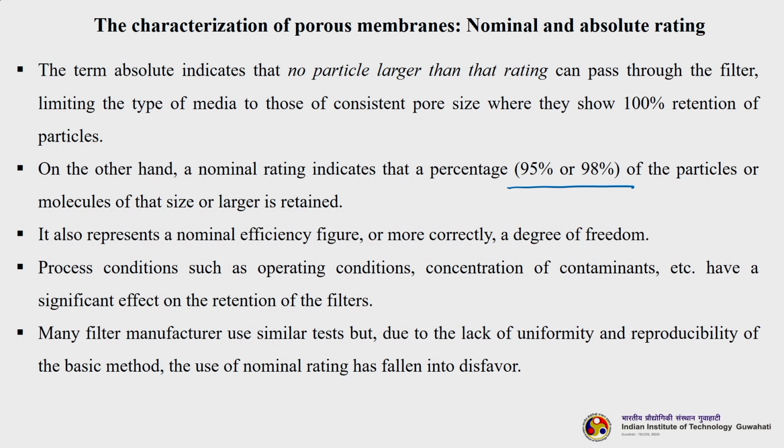It also represents a nominal efficiency figure, or more correctly a degree of freedom. Process conditions such as your operating conditions and concentration of solutes have a significant role in the retention of the filters. Many filter manufacturers use similar tests, but due to lack of uniformity and reproducibility, the use of nominal rating has fallen into disfavor. So, mostly whatever ratings we see nowadays are absolute ratings.